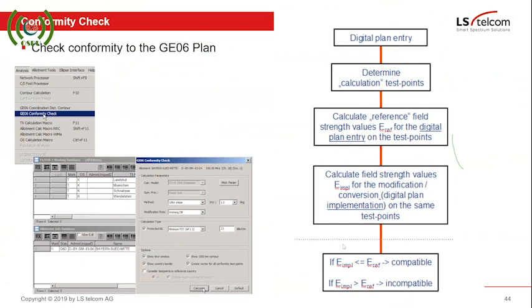Excuse me, if we add a new station to an old operational SFN, what do we have to do? Do the synchronization, a new synchronization. Okay, so if you add a new station and you can see there's a synchronization problem, then you can simulate it in your planning tool and you can put a delay in the transmitter.